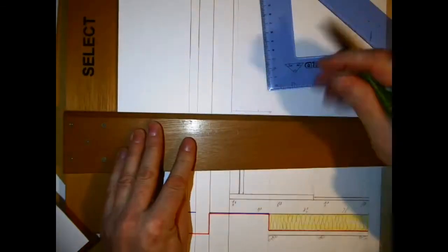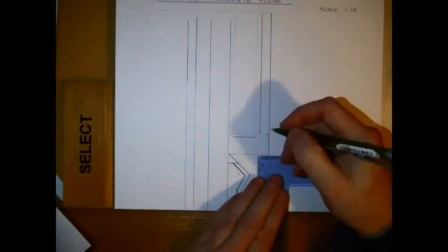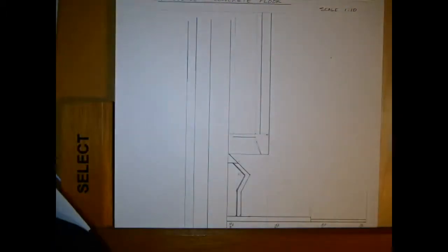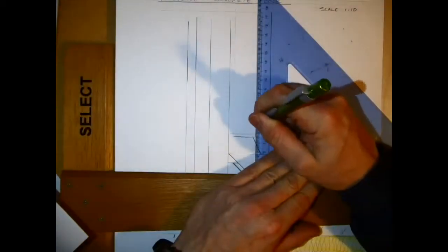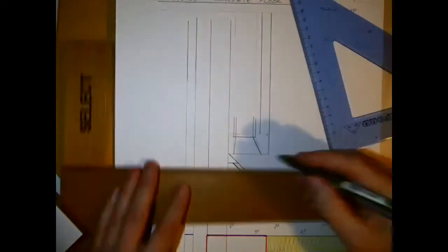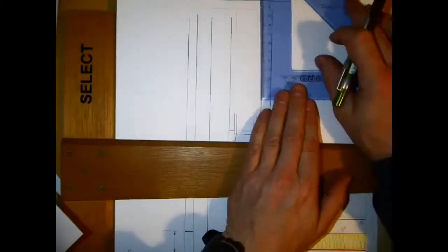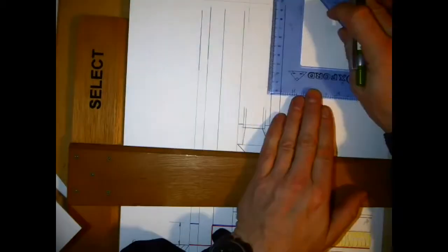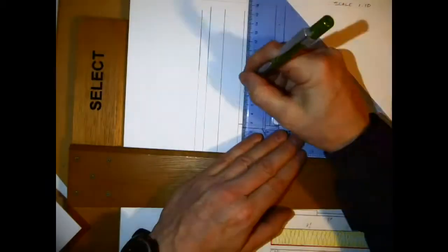And for the openings here as well, you can slow it down and take a look at the ruler sizes that I have. 150 from the front edge of the flue gathering to where the flue goes into it. You can see I've made a mistake here in the line that I've drawn for the flue. Sizes of the flue are also given as well. So I've come 50 from the bottom edge to get the inside line for my flue as well, as I'm going up here.